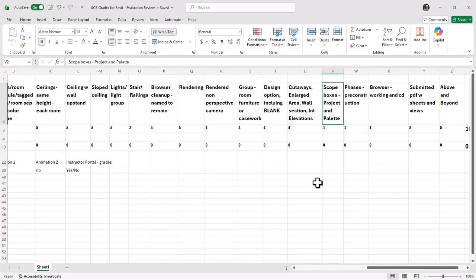Because at the end of the day, you could save your project as a template, and then you could delete the actual model elements themselves, but leave the palette, so that next time you create a project, you could use your interiors template and have all of the walls, doors, windows, furniture, lighting, whatever. You'd have it from the palette instead of searching for it. You could put the two views side by side and say, create similar and pop them into the model. That's something I've done for multiple firms.